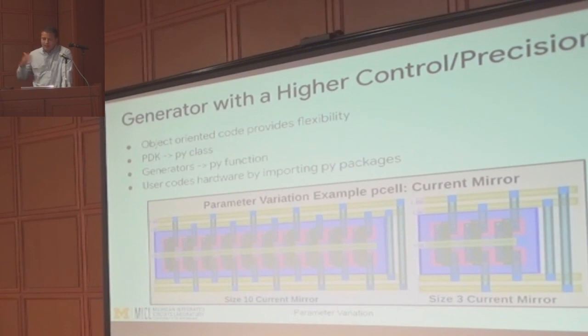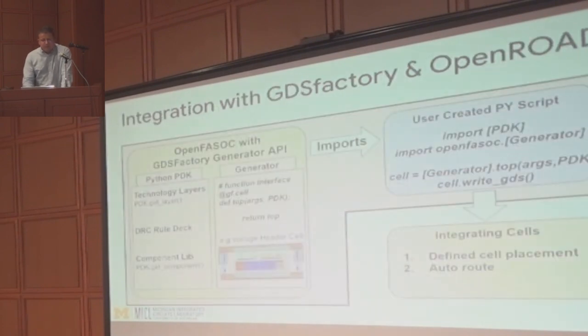We tested this and we're building these generators bottom-up, over and over. The generators are implemented as Python functions, which return a full layout stored in GDS Factory component types. These functions can accept arguments for automatic customization. The generators can also call other generators to produce hierarchical designs.